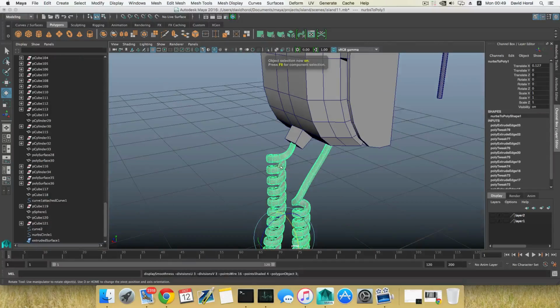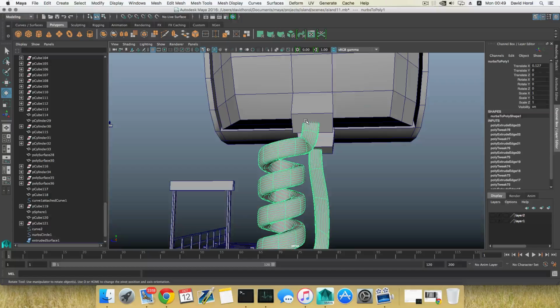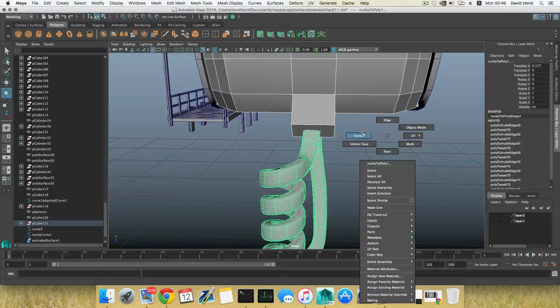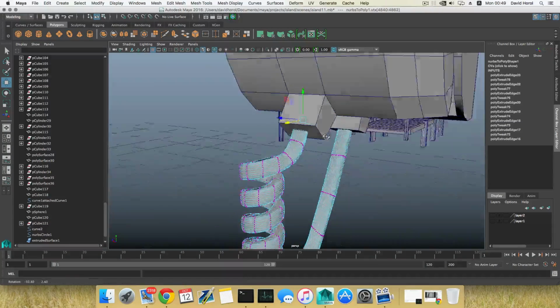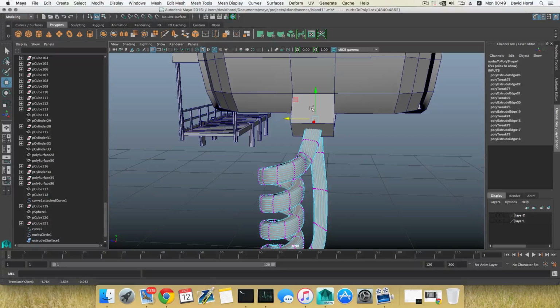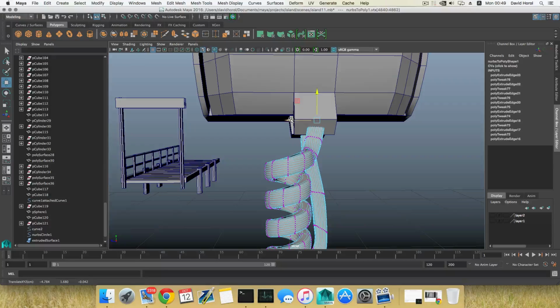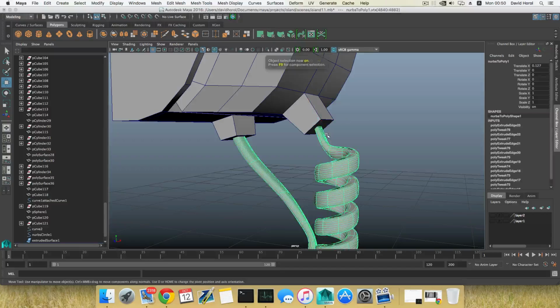You can press 3 to smooth the preview of this, and by that you will basically know better how this looks in position. Right click, choose vertices. I'm trying to grab all those vertices there inside. These are the last coil there, you see those, so just trying to position it a little bit better. Press F8, bring it back to object mode.